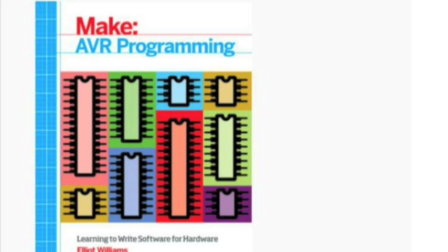The floating point version of printf takes up even more memory space because it has to load the floating point memory library, which isn't normally used. And so if you're on one of these chips that has only 4K of program memory and you're using half of the memory up just to print out the number 2.3, you're misallocating things. On the other hand, they do work, and if you've got a 16K microcontroller and you're using 8K of it, by all means use printf and make your life easier.